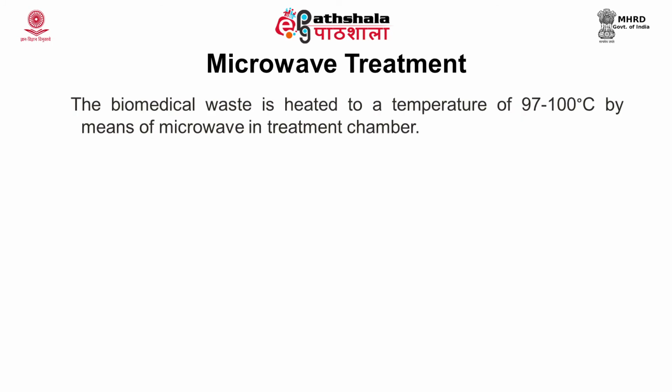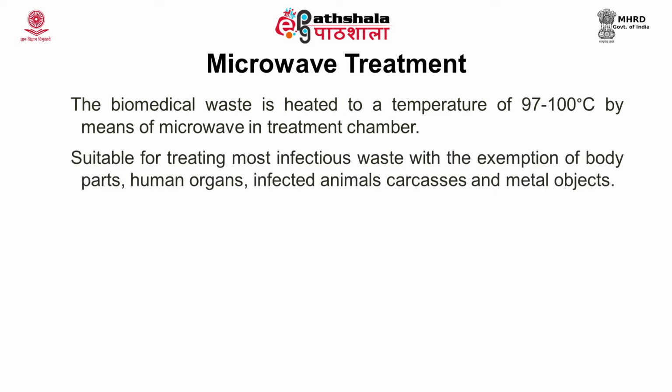Biomedical waste should be heated to a temperature of 97 to 100 degrees Celsius by means of microwave in a treatment chamber, which is carried out in the source itself without shredding. Shredding is a process by which waste is cut into small pieces. It is suitable for treating most infectious waste with the exemption of body parts, human organs, infected animal carcasses and metal objects.